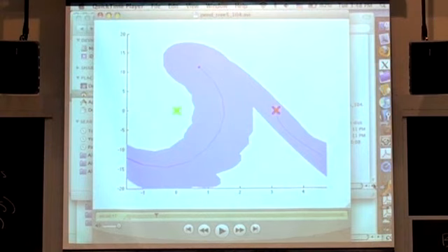So this is feedback motion planning happening. Now the cool thing is I told you about the multi-query idea. I told you about all these ideas, talking about making very dense trees that handle all these situations. If you know the basins of attraction of your existing controller, you don't have to build a very dense tree. If I were to pick another random point that was already inside my blue region, I'm not going to get a lot of value out of adding nodes inside that blue region. So let's pick another random point, and if it's inside the blue region, we'll throw it away. If it's outside, I'll keep it and I'll try to grow to it.